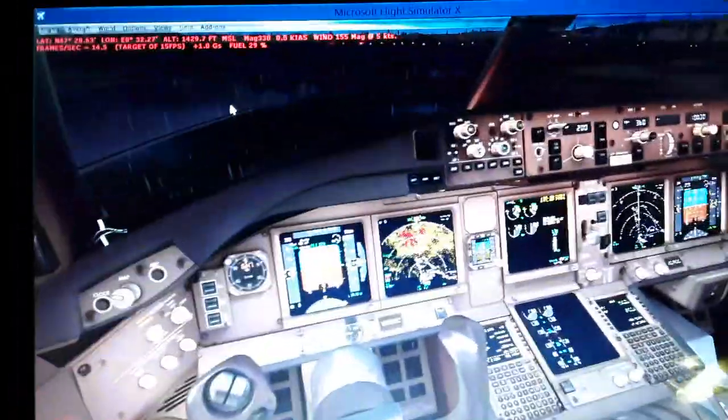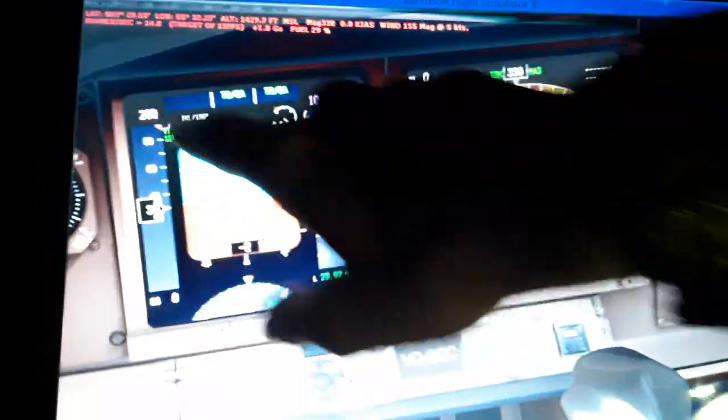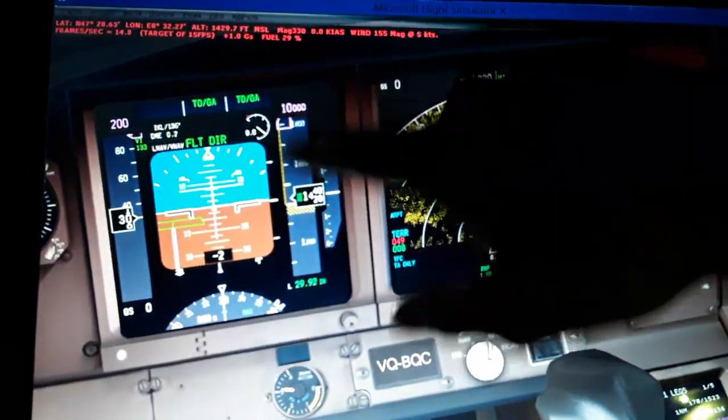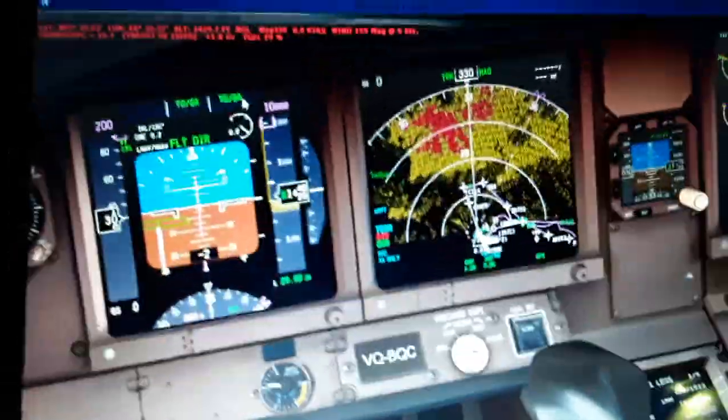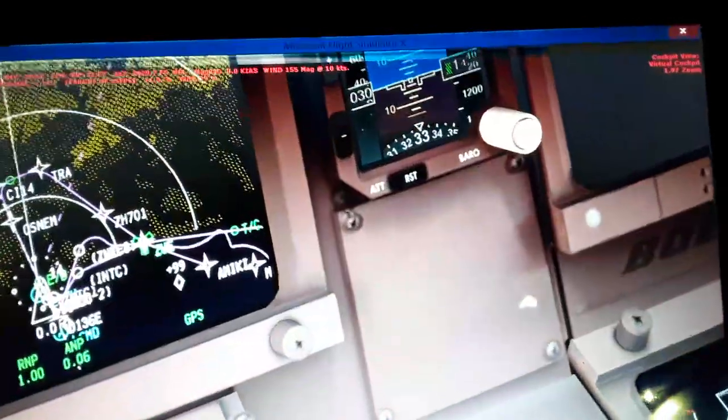We're going to have the magnetic heading, magnetic north pole and true north pole, the magnetic variation again. So you're going to see all this data here. You can see we start showing this. I hope you see it clear. We have the airspeed indicated, the airspeed selected, the barometric altitude. You can see everything in the primary flight display, all the data. I'm going to show you then later when we make the flight.